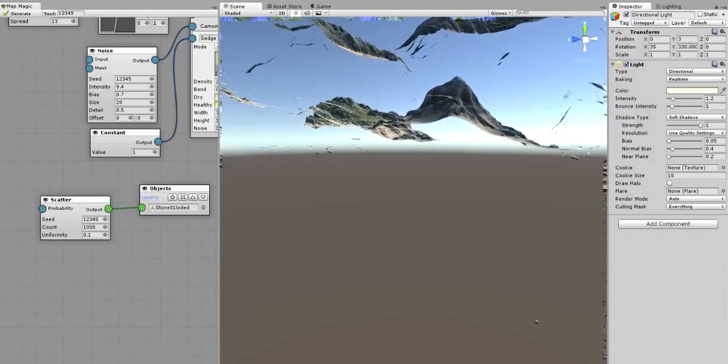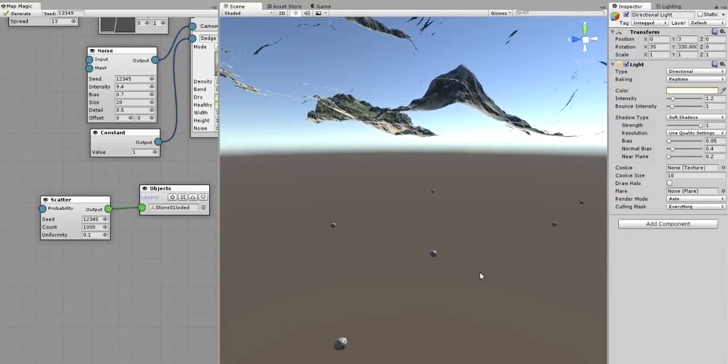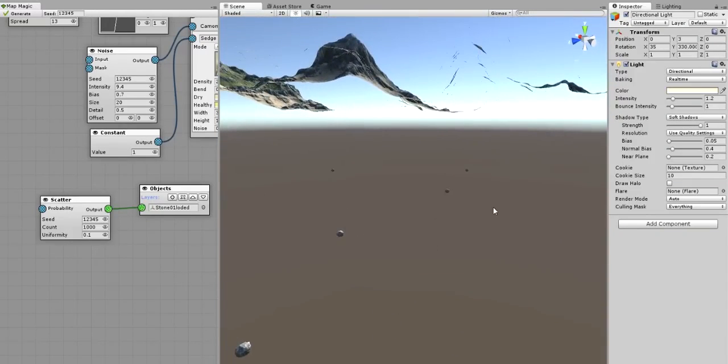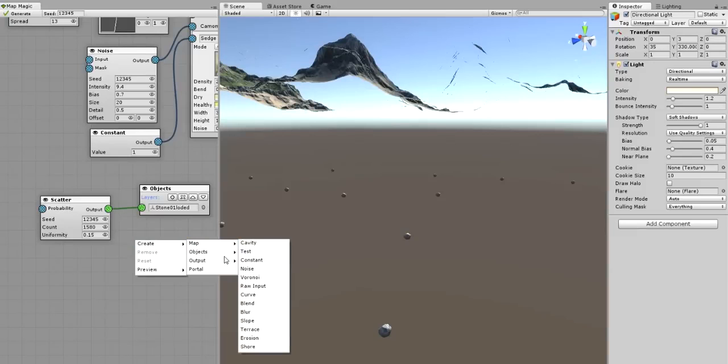Let's get down, below the water level, down to the zero level of the scene. Here you can find the stones. Stone objects know nothing about the heightmap yet, so they are placed here. The count parameter of the scatter generator determines the quantity of the objects per terrain. The uniformity is how evenly they are distributed. I'm afraid it's hard to show it in such a case. Anyways, this parameter shouldn't be very large. Usually 0.1 is enough.